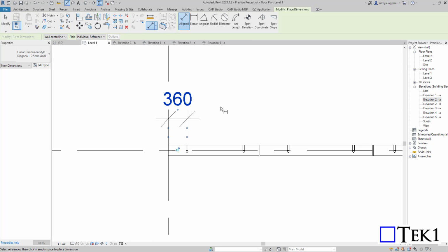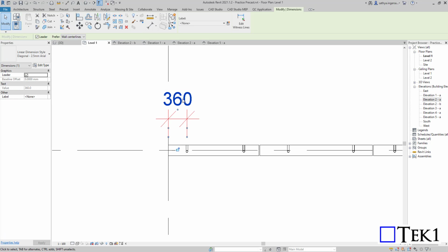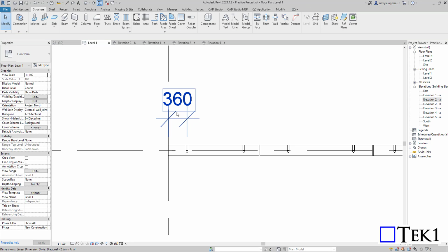So it's done. Now we are able to see a dimension for the component is provided, but it still is not over. Then I just need to convert this dimension into a parameter. Normally in the last block we saw that the parametrics might include the data or identity data, but in this we are just going to convert the dimension into a parameter.